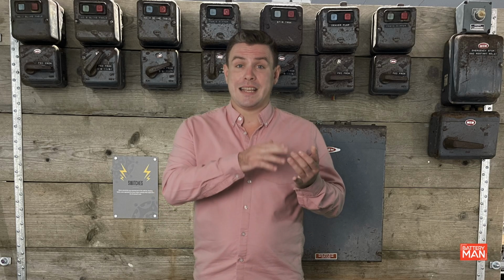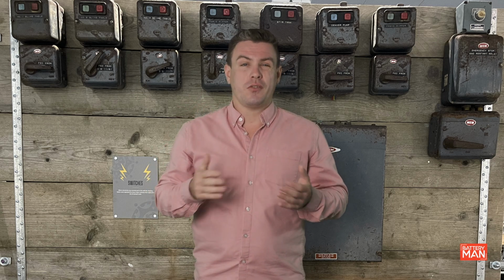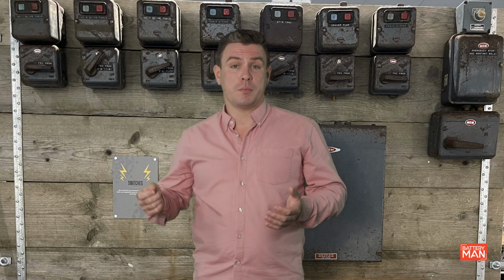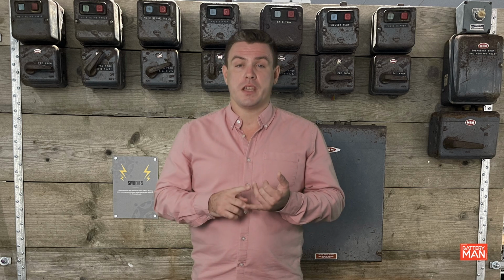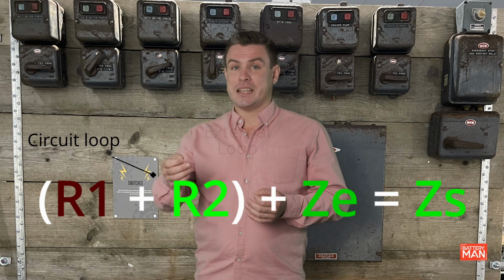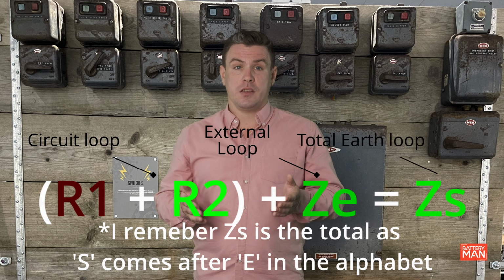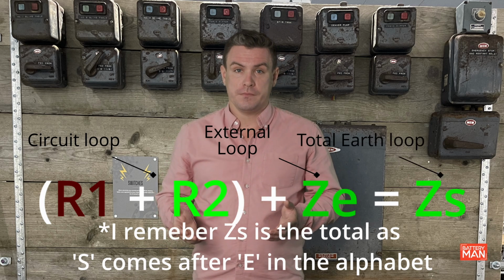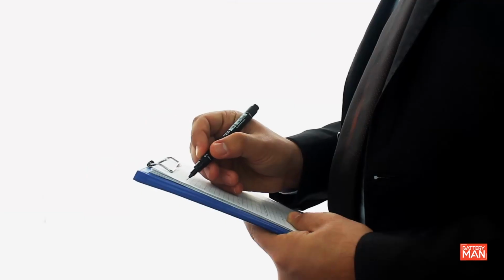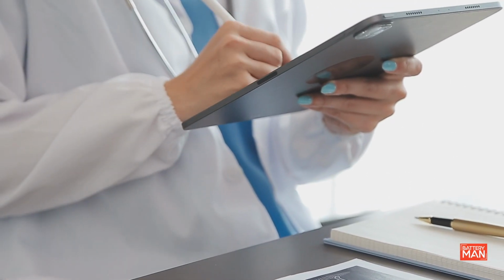With the earth reinstated back to the earth block, we now test each circuit, whether it be sockets or lights, on a live circuit. We'd test at the furthest point, or the one with the highest value of the R1 and R2 measurements for each circuit. By adding the Ze we previously got to the R1 and R2 values that we just tested, we'd get the Zs for each circuit. All these values we'd want to note down. I wonder how many electricians are recording these values with pen and paper, and how many are using things like iPads.